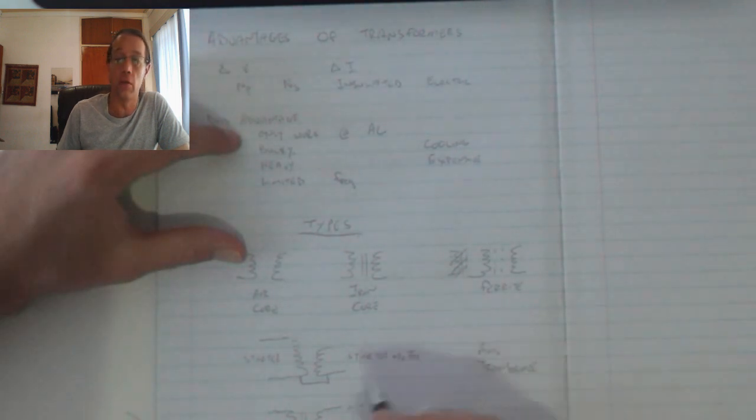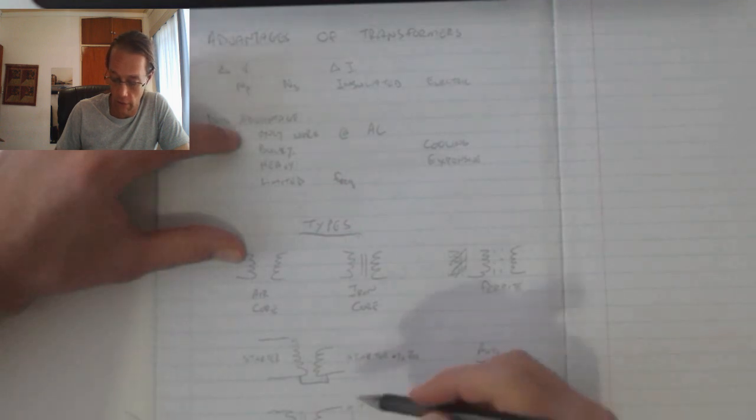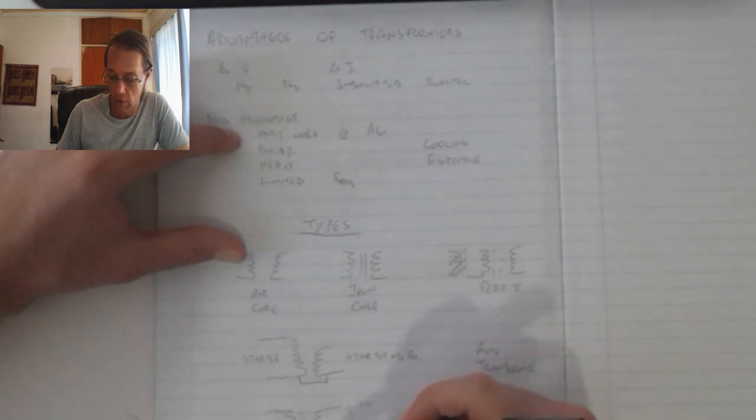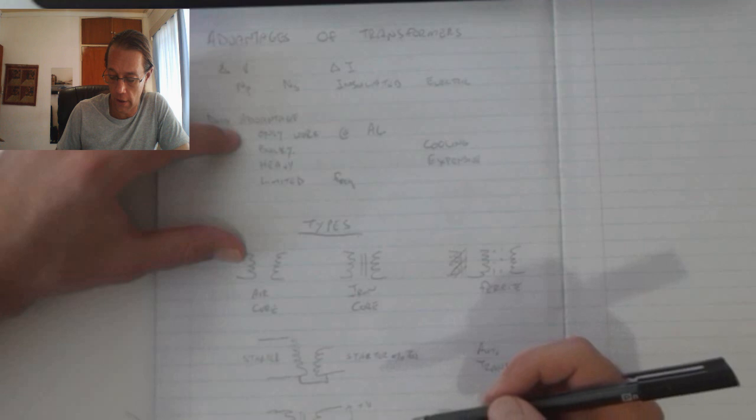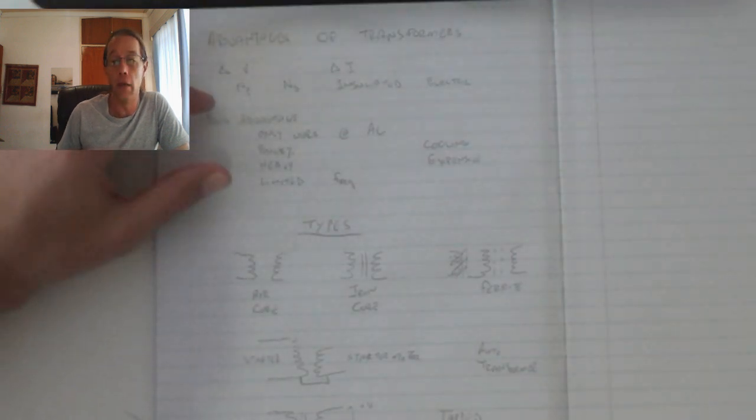With a tap transformer, if this is exactly in the middle, it's called a center tap transformer. If that point is above or below, then it is just called a tapped transformer. It is possible to have multiple taps on the secondary side of the transformer. I've also actually seen taps on the primary side of the transformer as well.